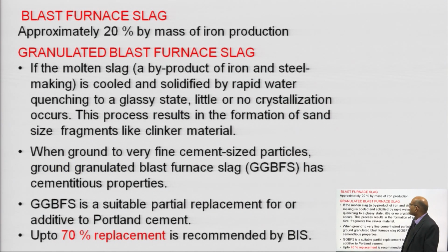Blast furnace slag is about 20% of the mass of the iron. And granulated blast furnace slag: the molten slag, a byproduct of iron and steel making, is cooled and solidified by rapid water quenching to a glassy state, that is important, with little or no crystallization. So, crystallization should not take place. This process results in the formation of sand-size fragments like clinker material.